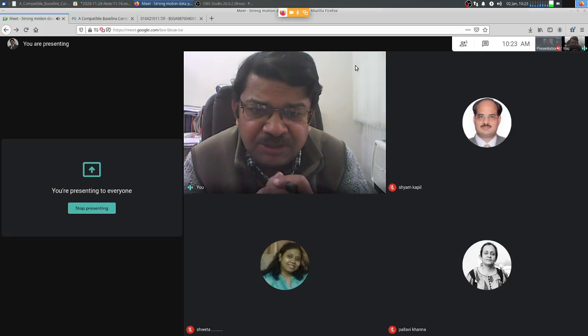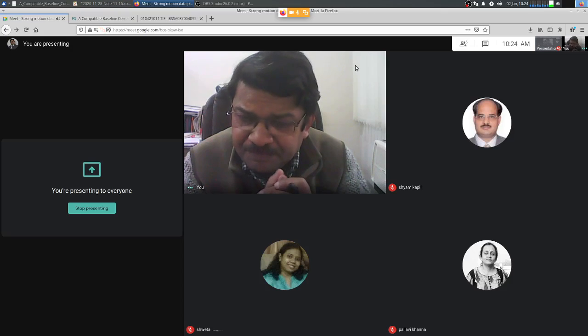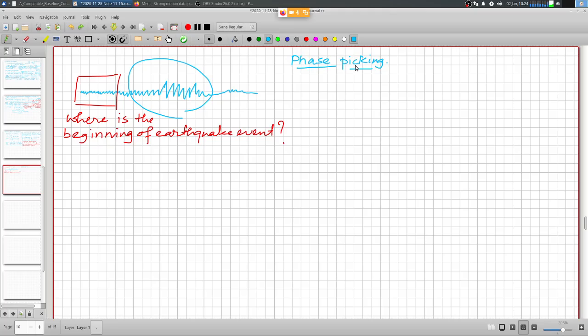I hope you are aware of this phase picking, where you do this by considering the STA by LTA average, right? That is short term average and long term average. We take the ratio of that, short term average divided by long term average.